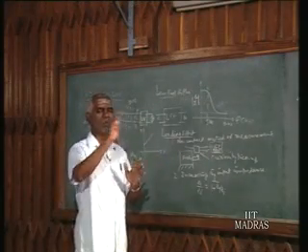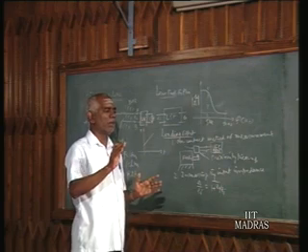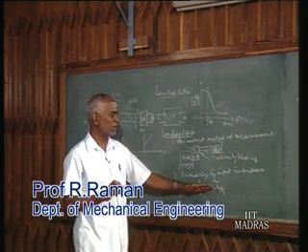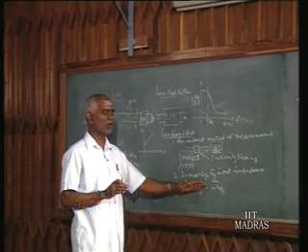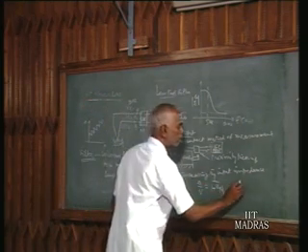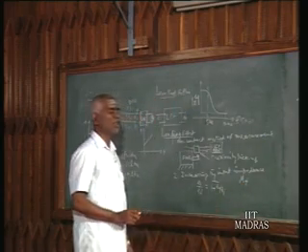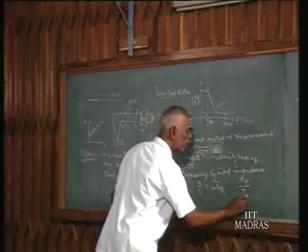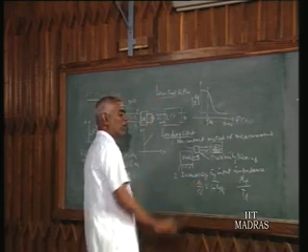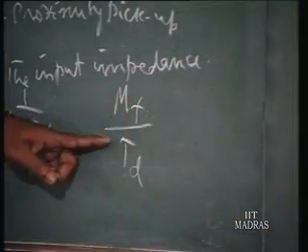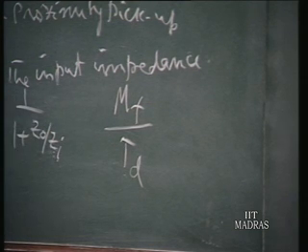So for a smaller torque, the coil will deflect more. But what we have achieved in this is that the amount of deflecting torque has become small, and suppose MF is the friction in the pivot, the ratio of MF to the deflecting torque TD becomes larger. When the MF to deflecting torque ratio becomes larger, then the error of the instrument is larger.